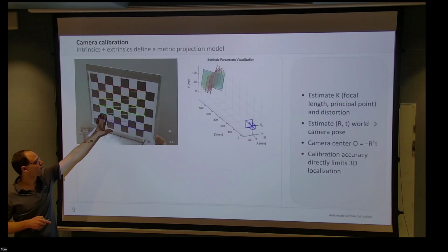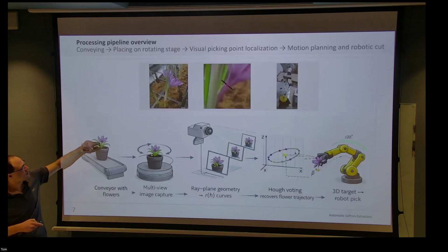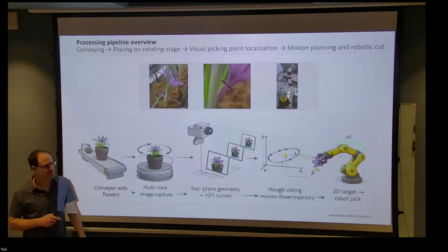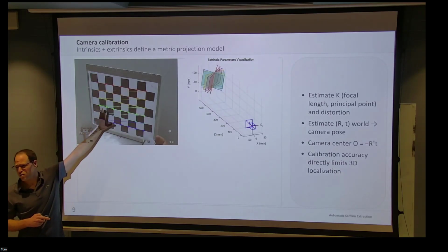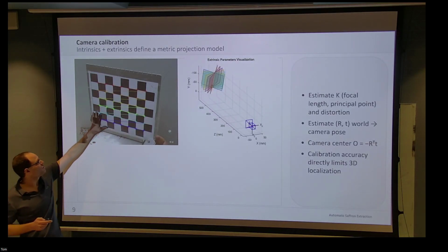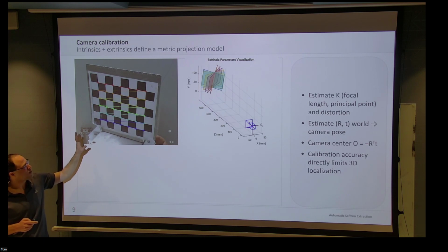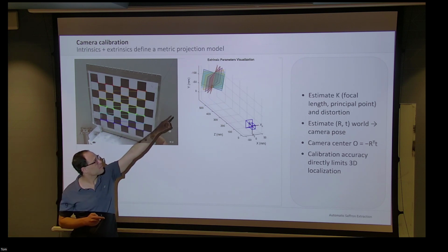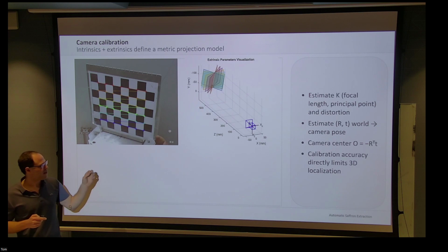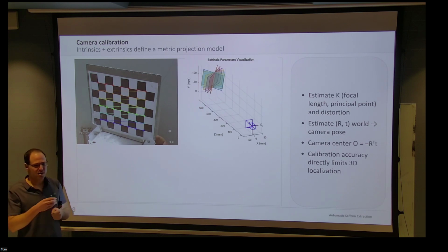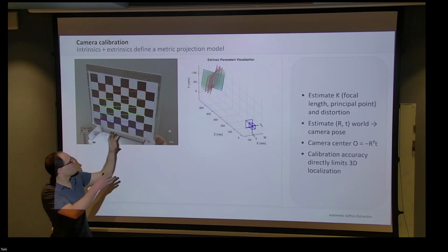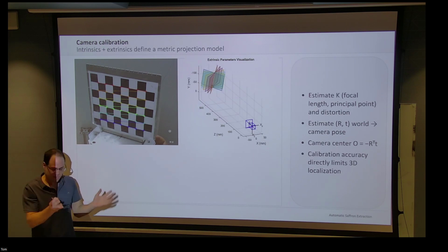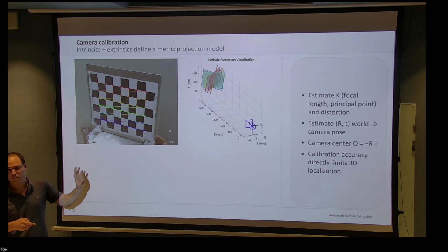Okay, this is the calibration board. We put it on our rotating stage. You saw it here. We put this calibration board on this stage. Then we use the chessboard, which probably all of you are familiar with, where we know the points of the chessboard, and we make a calibration. One board is enough, but we will rotate it many times to get the best calibration data, even with a low resolution and cheap camera, specifically for the region that interests us, not the corner, not the distortion. We want to calibrate exactly around the area that we need.